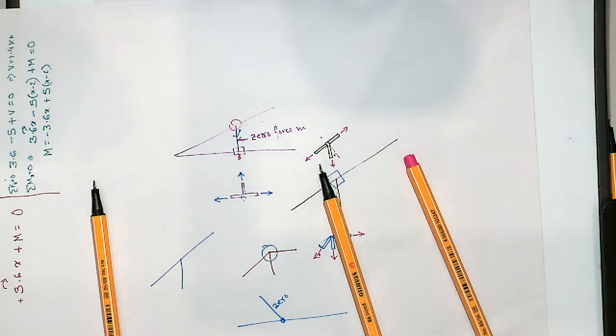So this load must go through that member and this member. Okay? So if two or three members connect at a point, then you can find out quickly whether that would be a zero force member. So in this problem, AB would be a zero force member. Similarly, these would be zero force members. For other members, we are not so sure. It may be, it may not be. For example, this vertical member connects at the top, and there is a load, so this can take vertical load, so not necessarily this would be zero, and the inclined member may not be zero, or maybe zero, but we cannot really say which one is zero or not.